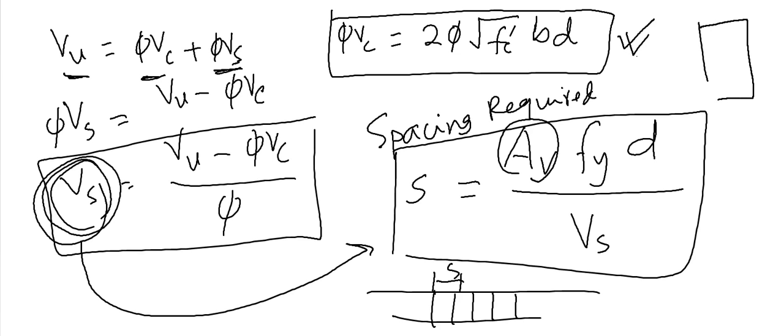So this is your beam reinforcement. Here you are using this reinforcement, the area of this bar and this bar. Say if it is number 3 bar, then here your area will be 1 here, 2 here. So 2 times 0.11 inch square. If you use number 3 bar, I can memorize that number. For number 3 bar, the area is 0.11 inch square. So 2 here.